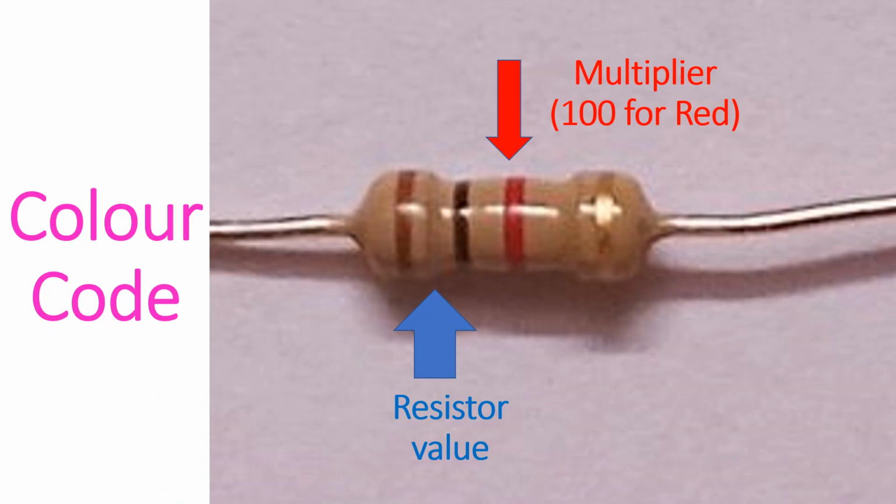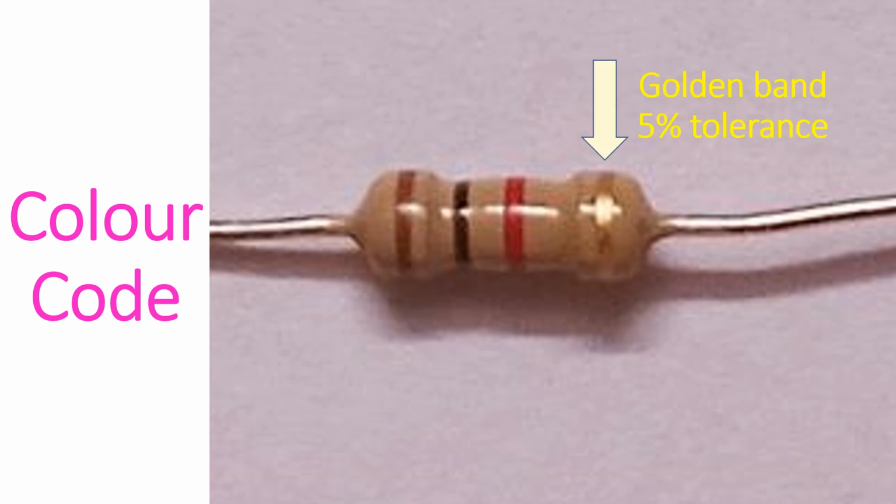The value of the resistor is indicated on the resistor with a color code. The resistors shown here have a 4-band color code, which is the most common one in use. First two bands indicate the resistance value, which has to be multiplied by the code on the third band. Fourth band indicates the tolerance. All the resistors shown here have a golden band for the tolerance, indicating 5% variation above or below the coded value. If there is no tolerance band, the tolerance is presumed to be 20%.